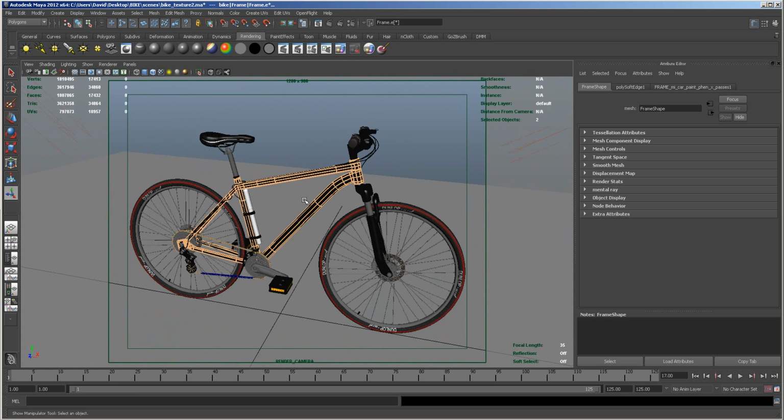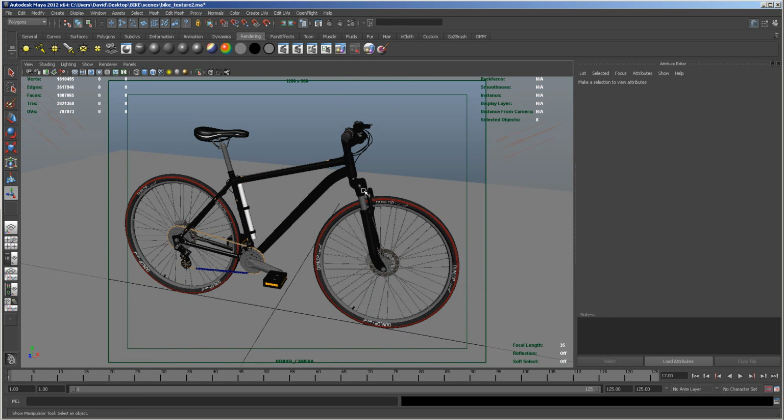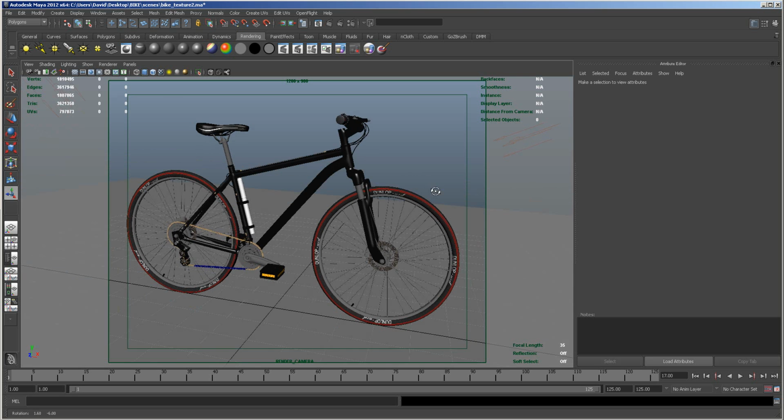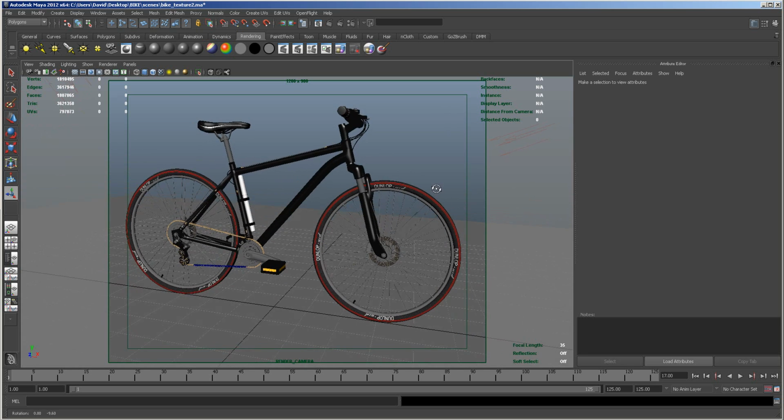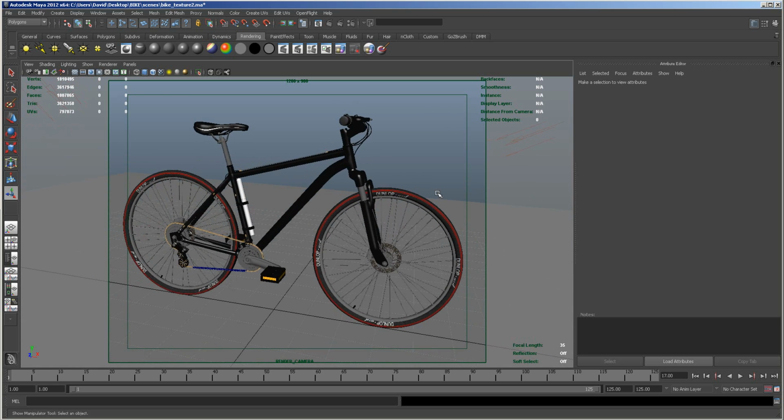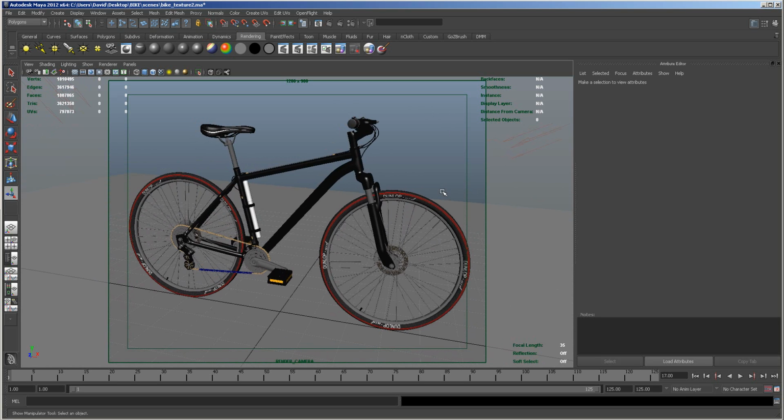So I'm going to do another course now where it's rendering out this bike, and we're going to look at things like adding an HDRI map to it to create a kind of environment. We'll set it up as a turntable, and we'll show about rendering out the shadows and final gather and all these sort of things that will really improve the final image that we can render out in render passes and put together in something like Photoshop, or if we do it as a rendered out sequence, we can take it into something like Adobe After Effects and comp it all together within that program.